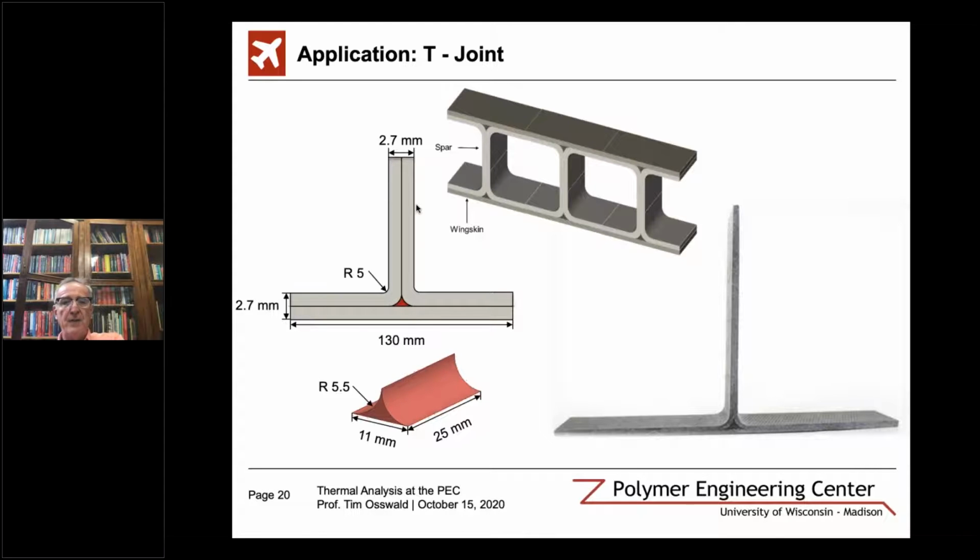This hybrid structure would be, for example, a wing skin, which has spars or ribs between. When you place the prepregs on the wing skin, and where the prepregs come together on the other side to create the rib, you create a hollow region, which is called the deltoid. Of course, this weakens a wing skin or weakens a part.